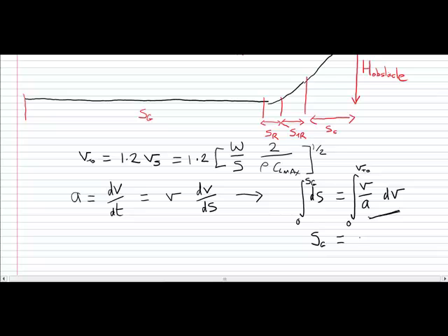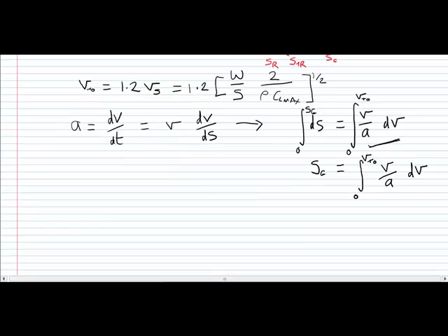But fortunately, as I mentioned in the lecture, we've got a MATLAB code that will numerically compute this integral for us. That's essentially what is going on inside that calculate mission profiles routine within the MATLAB program that I've given you. But of course, to compute this integral, we need to know what the acceleration of the aircraft is as a function of aircraft speed, v.